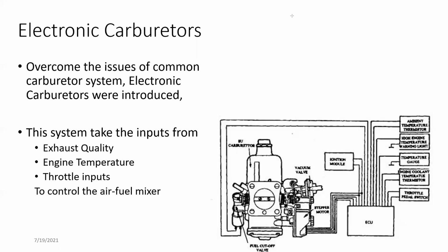So to control this air fuel mixture, they actually use another valve to control the vacuum, right? They control the vacuum inside the manifold. So this was a very common method used in the 1980s. Vehicles such as the Toyota Carina, 1980s Carinas, these Coronas, all these cars, and even the Bluebirds, all of these actually have this module, right?